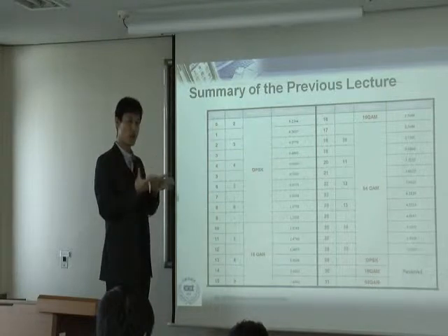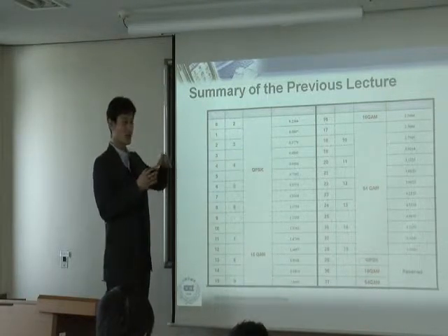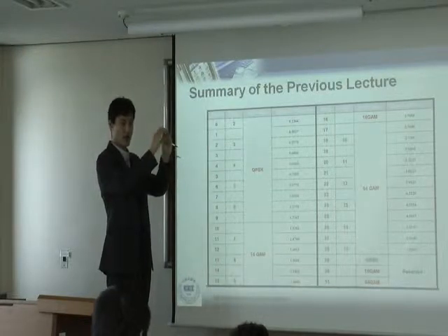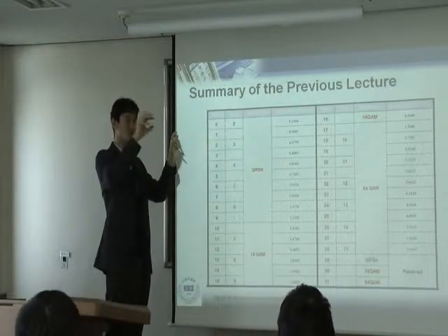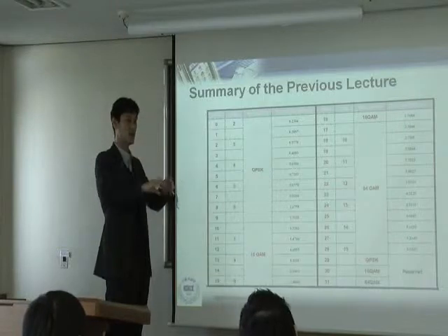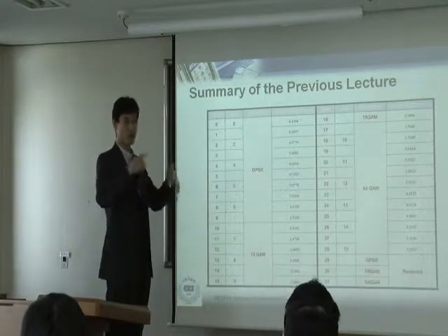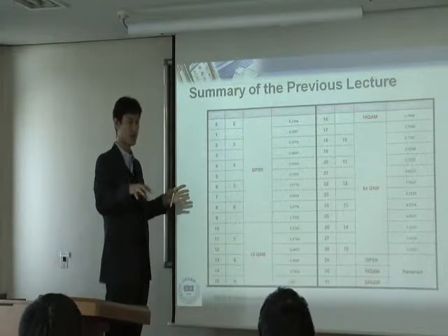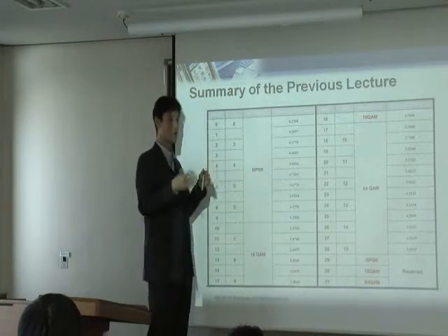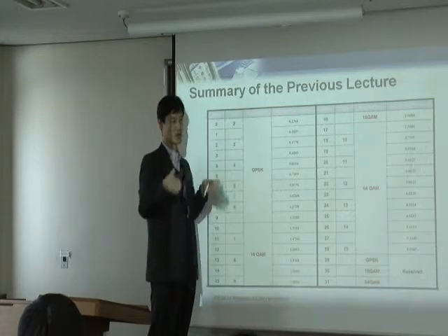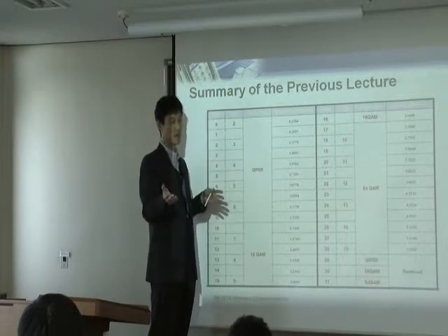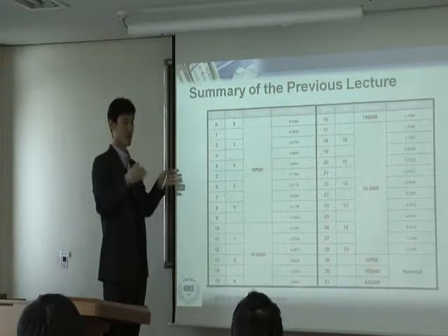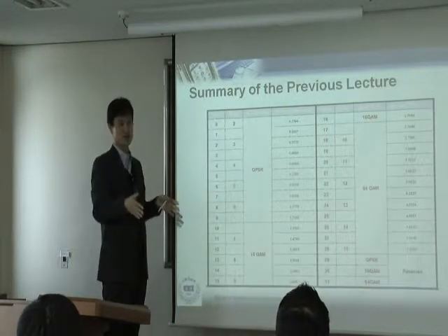Typically, when you do the rate, the coding, what you do is you have an input of some size. Then you put some redundancy on it, so the output from the encoder should be larger because you added redundancy. The coding rate basically means the ratio between these two. So it cannot be higher than 1. 1 is the maximum because 1 means you have no redundancy; this one and this one are the same.